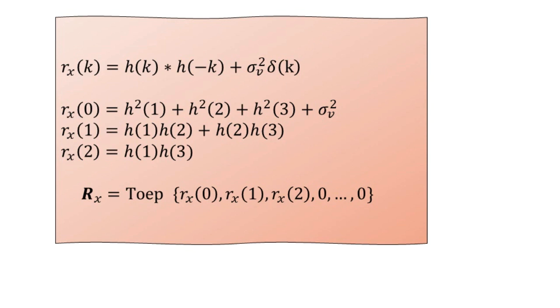Now for the autocorrelation matrix, there are the eigenvalues which affect the convergence of the adaptive filter, and they depend on the value of capital W as indicated in the previous equation, as well as on the size small p of the autocorrelation matrix, which is equal to the number of coefficients in the adaptive filter, what we can call the order as well here. So there can be a brief tabulation for the maximum and minimum eigenvalues of the autocorrelation matrix.